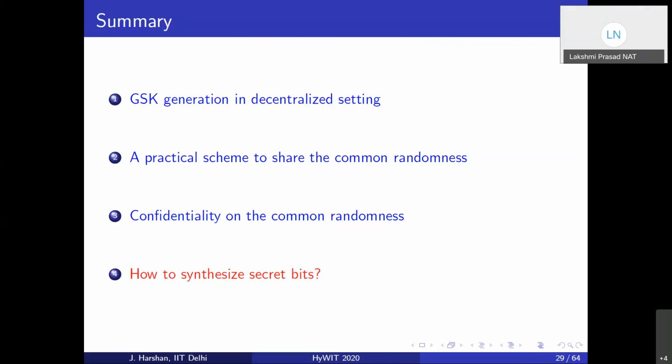Sure, that's a good point. Now, if we go with the assumption of circularly symmetric Gaussian random variables, we can as well unfold them into two real random variables, and then you could look at extracting bits out of those amplitude levels. So that would in fact give them twice the number of bits, because you're unfolding the bits into real and quadrature. Okay.